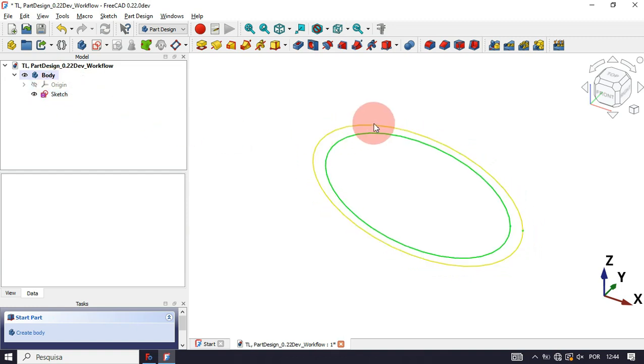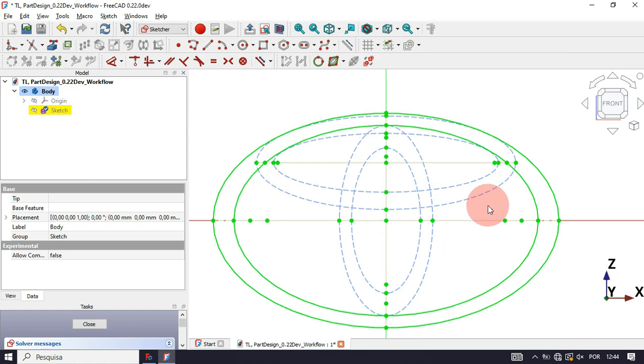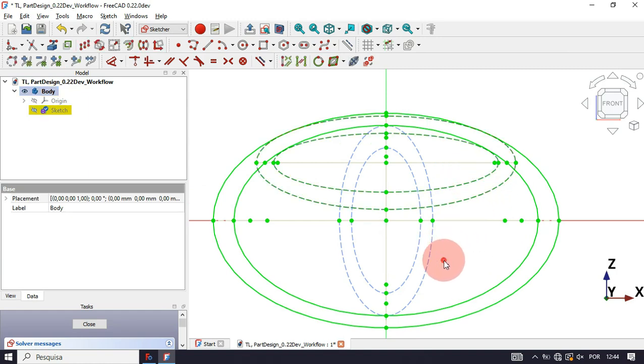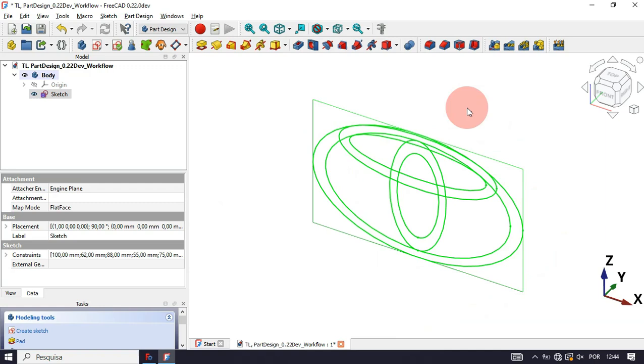And next, what you'll do is make all pairs of ellipses visible. Double click on the sketch, and now zoom in, and what you need to do now is select these two pairs of ellipses here, and then convert these to normal geometries. To do that, we need to click on this icon here. Okay, and now we have normal geometries. And now skip two times.